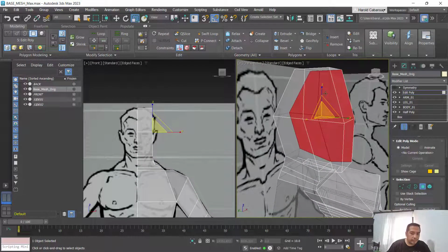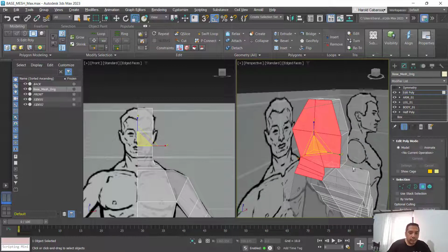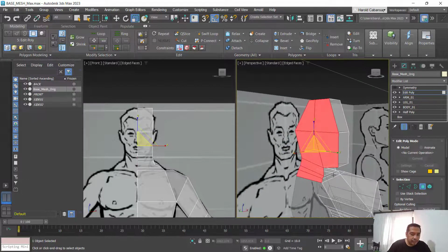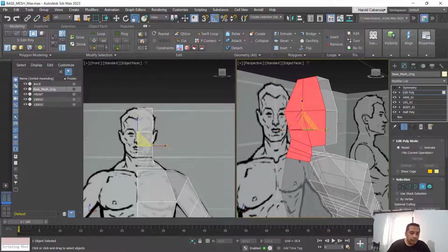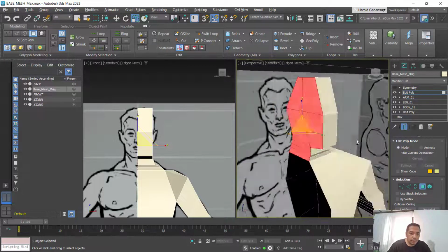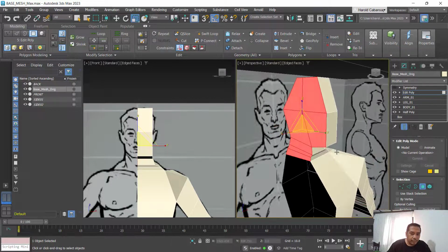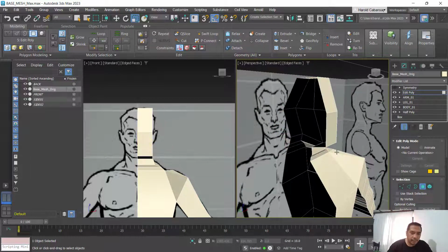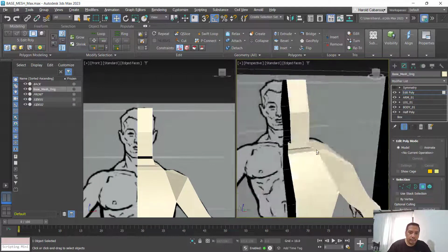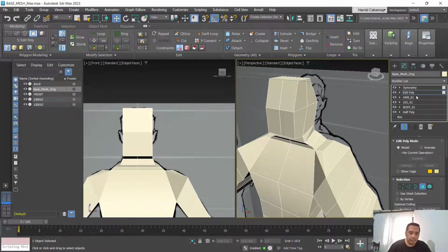I will now select the other or the inner portion, these ones, making sure that there are no polygons once we do symmetry. Now, you have to be sure that there are no polygons there. There should be no polygon present within the half of the symmetry. So I will press delete. I have them deleted now. So I can turn on the symmetry there.